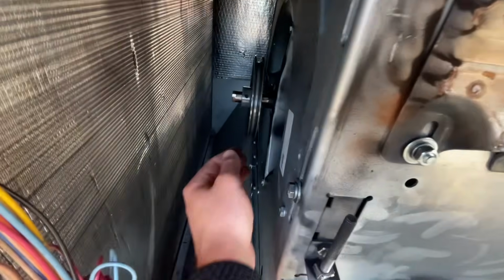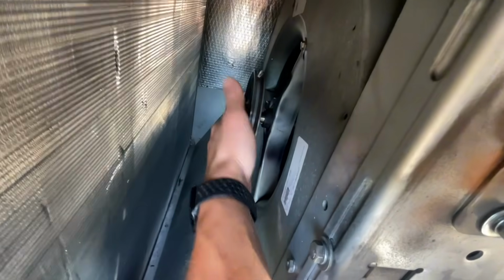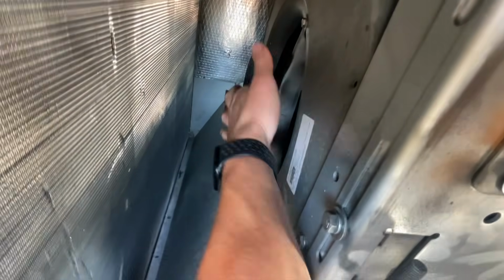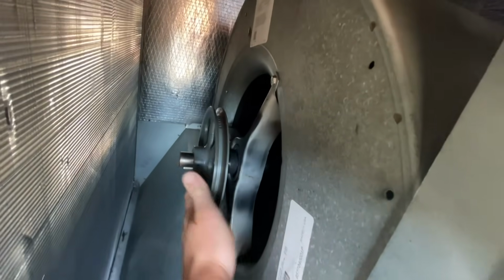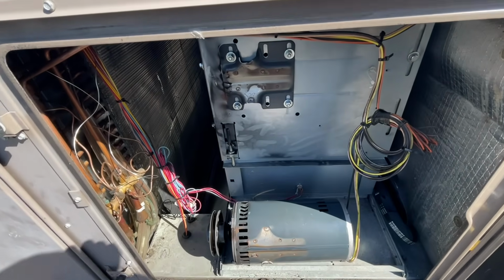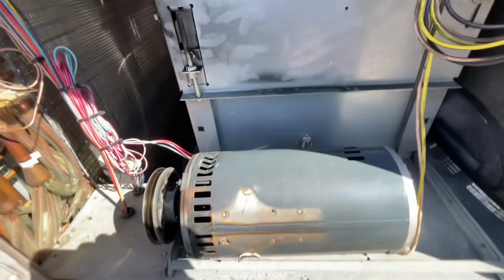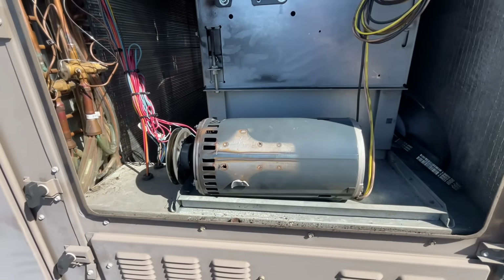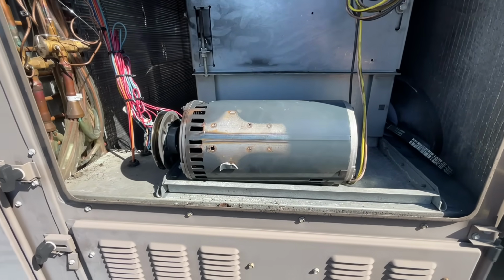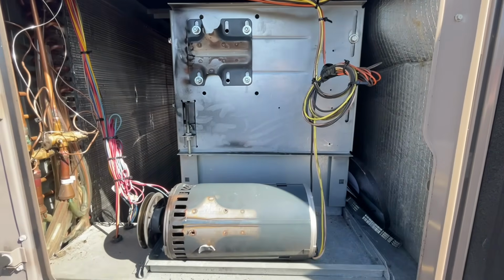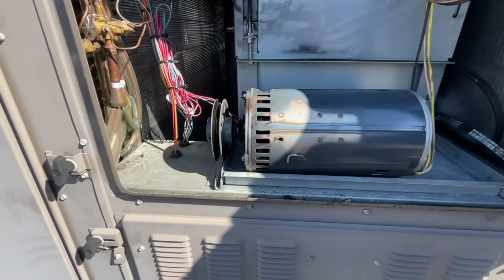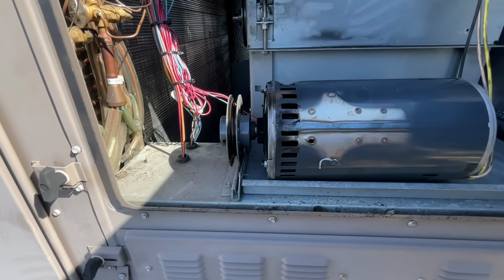Unreal. Blower pulley issues maybe. Bearings, they can be a problem too, but no. Those bearings actually look like they're in good shape. There's no play on that. It's running smooth. Our blower wheel isn't grinding against anything. Wow. What a shame, because that motor there is still in perfectly good running shape. Well, minus the bracket, but they're gonna have to change this entire blower motor. And we might as well get a pulley while we're at it too, with the new belt.